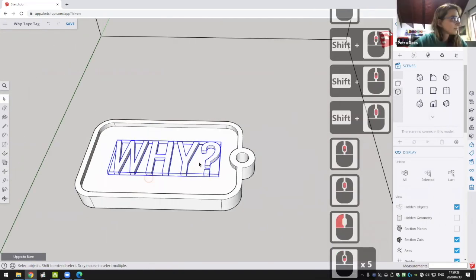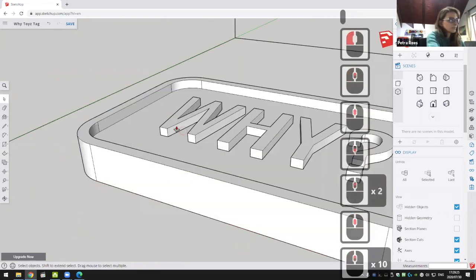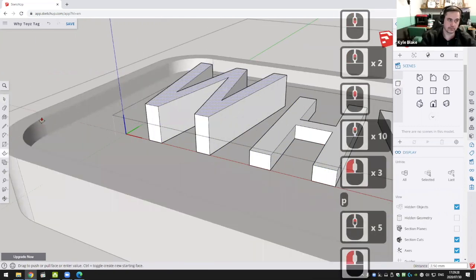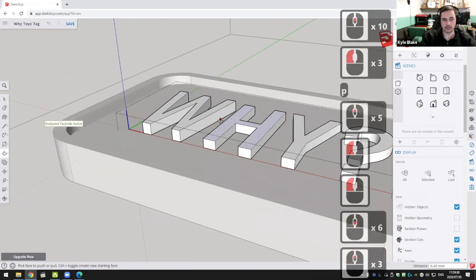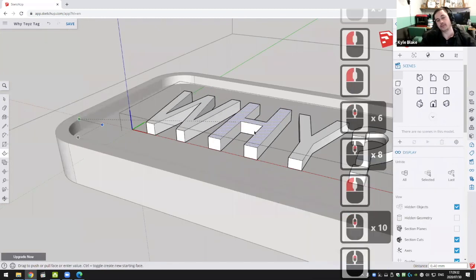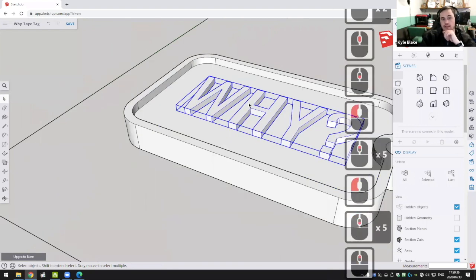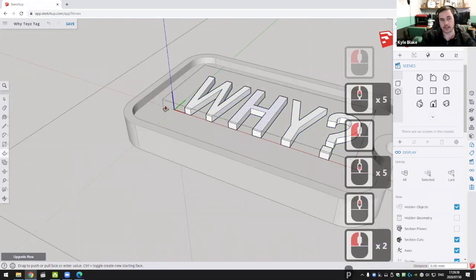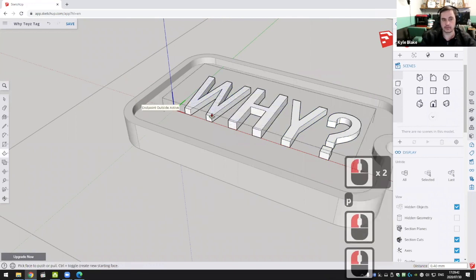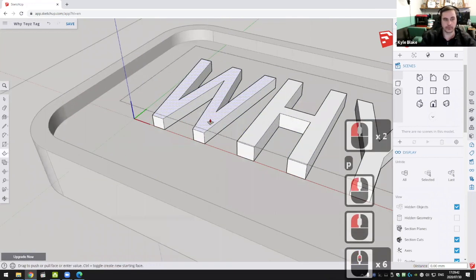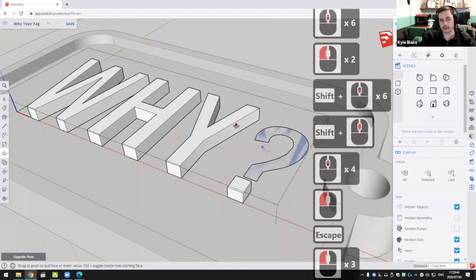Thank you. No problem. When you scale it, it will scale the letters down as well. So if you've brought your text in and it's still a component and you want to edit that, you can double click it. Double clicking will open up the model or the group to allow you to go and edit this.